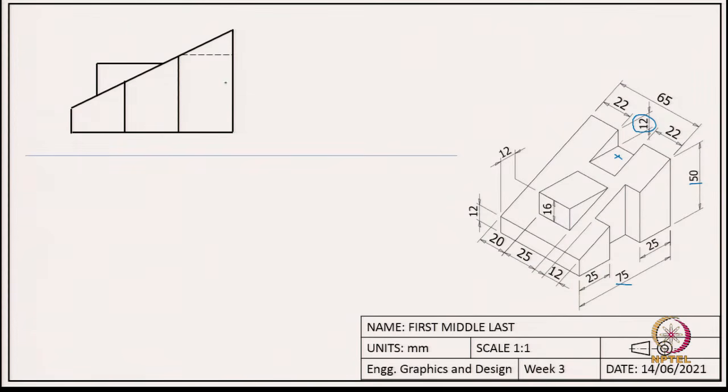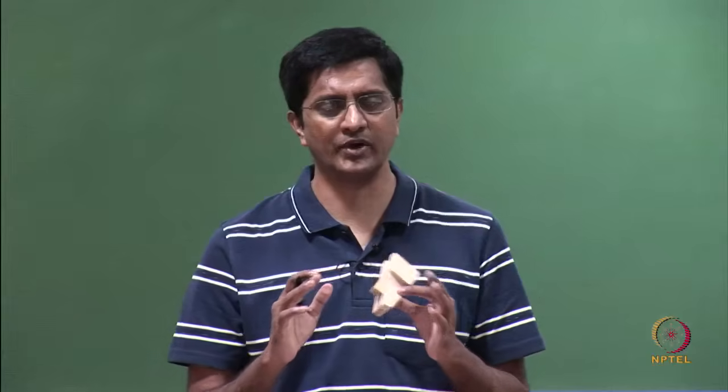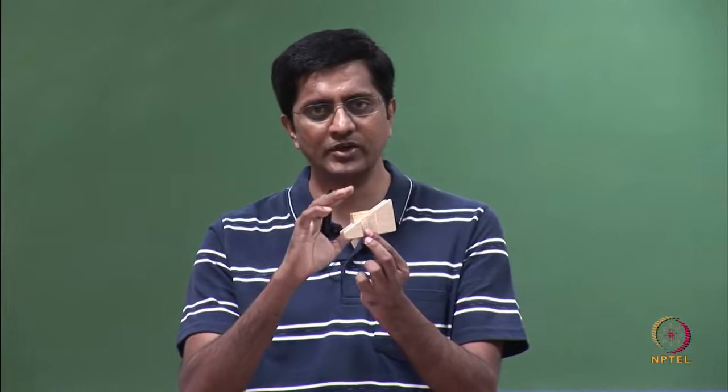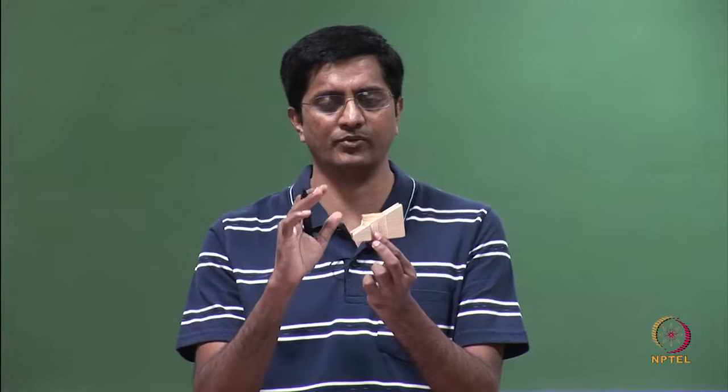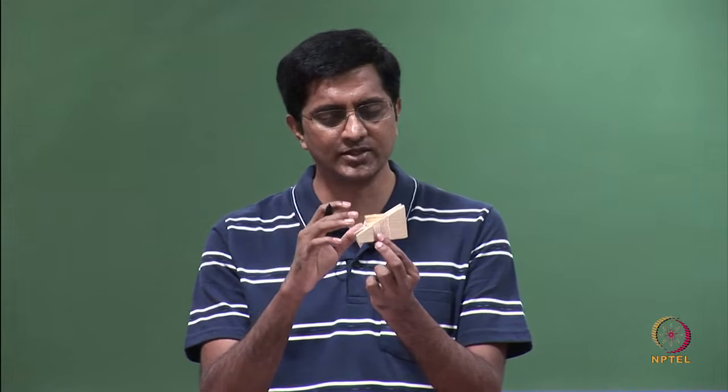So, as we all know, for the outlines we use thick lines, whereas for the hidden lines we use narrow or thin lines, and we use a dashed line to say that it is a hidden feature. Okay. So, this completes the front view. So, we have captured each and every detail of this object in the front view. Now, let us move ahead and draw the top view.